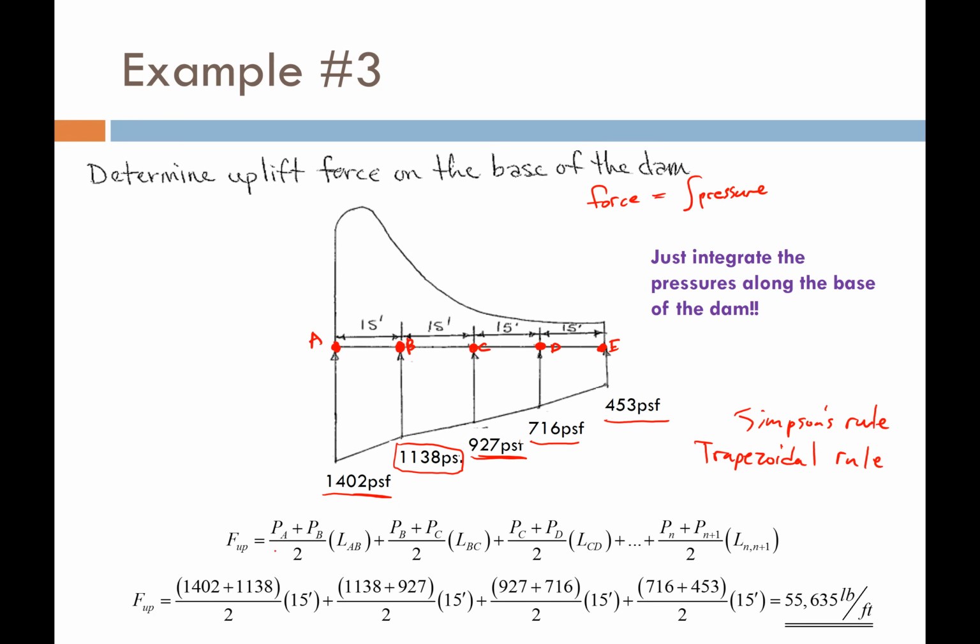In the calculations down below the figure is exactly what I did. All I'm doing is taking the average pressure for each one of these blocks of pressure down here on the bottom of my dam, and summing the area of them.